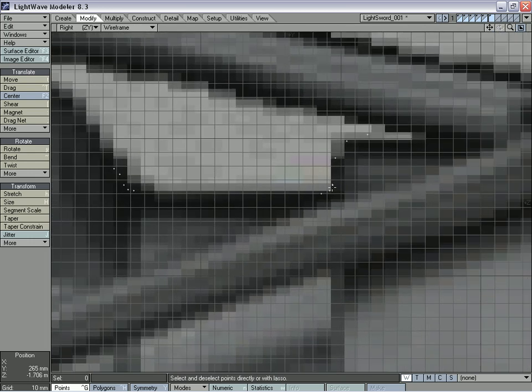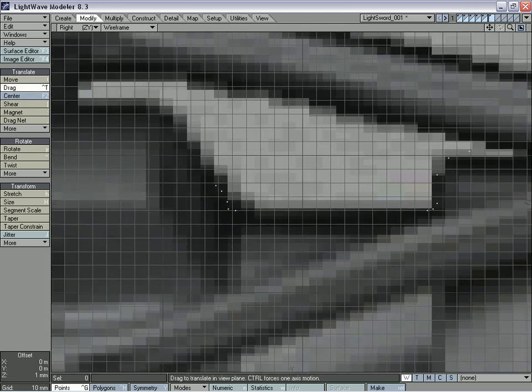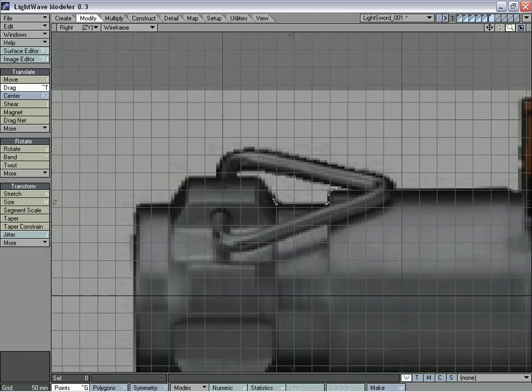And now we can go in here and delete this point, copy and paste, constrain, pull that down, and the same thing over here, delete this point, copy and paste, move it over. The move tool is T on the keyboard, and then we'll drag that into place. And this is angled just a little, so we don't need that to be perfectly lined up.